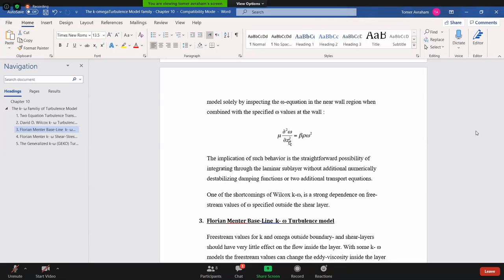And the funniest thing is that when we talk about two-equation models, we say they are closed, right? Remember, they are closed because we don't need to guess anything. We have two transport equations. LES is not closed because you have to guess the size of the filter.